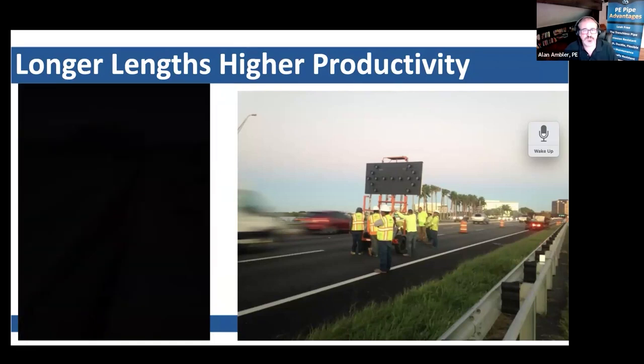In the picture on the right for a City of Tampa project here, they were using pipe bursting to be able to replace an existing cast iron main, but you still have to make excavations. The actual act of moving that MOT out into traffic and taking it away took up 1 hour of their limited 10-hour window for construction. Then moving the construction excavators to the pit site and taking them away also took another hour. So 20% of the productivity, the job site day allowance that they had, was just getting the equipment to and from.